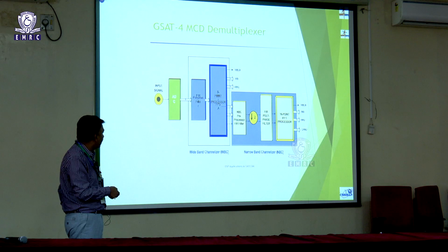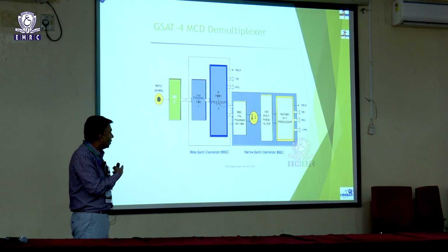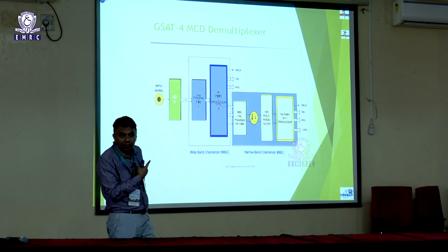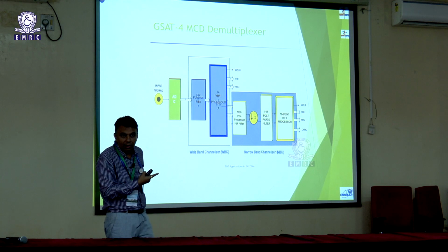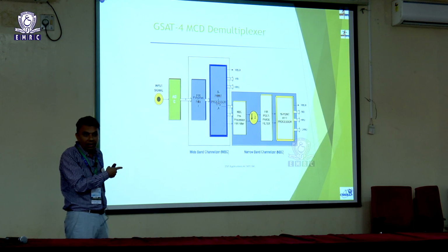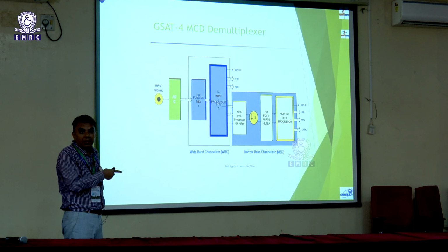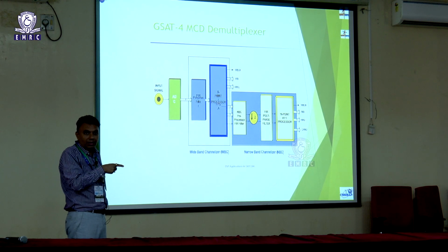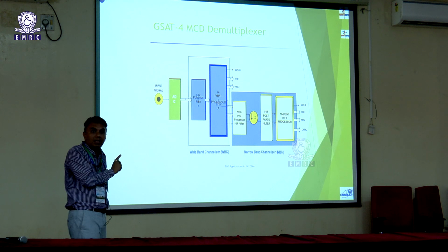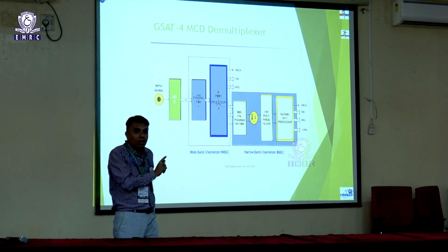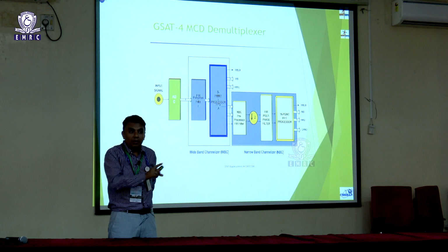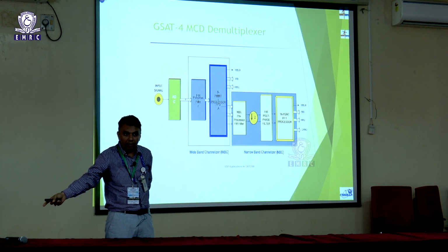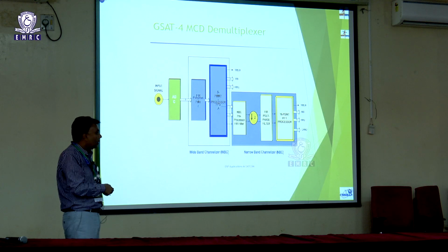I can show you some detail. This is the architecture. If you see this, we are using the multi-rate signal processing concept, a polyphase DFT approach, to do the data demodulation. This way we have developed the complete demodulation. I am not going into algorithm design, otherwise it would be an altogether different lecture, but I am showing what technology we are using. Without working in the RF domain, we down convert all the data to a common IF, and from the common IF we do the data demodulation using the multi-rate concept. So this is one part.